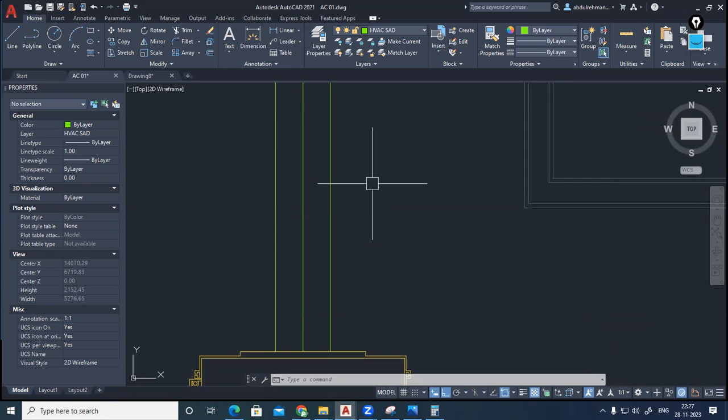The air coming out from the machine is approximately 13 degrees Celsius and 100% relative humidity. So sometimes condensation will happen in the machine mouth, even if we are designing it perfectly. Sometimes condensation will happen inside. Depending on that, if you are using neoprene, that is not a big issue. But canvas cloth will absorb this moisture. Later, that will enhance fungal and algae growth. That's why neoprene is the good material.